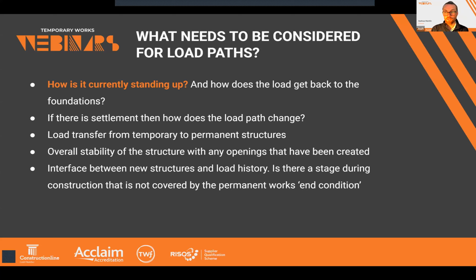And sometimes it's not, when there is a structure being demolished anyway. The load transfer from temporary to permanent structures is really important and requires some thought. The overall stability of the structure as well, taking into account any openings that have been created. Are we creating a structure that looks like a block of Swiss cheese, putting lots of holes in it, doorways, floor openings? And if so, we need to have a lot of confidence in the load paths, as there will be very little redundancy in those supports in the structure.